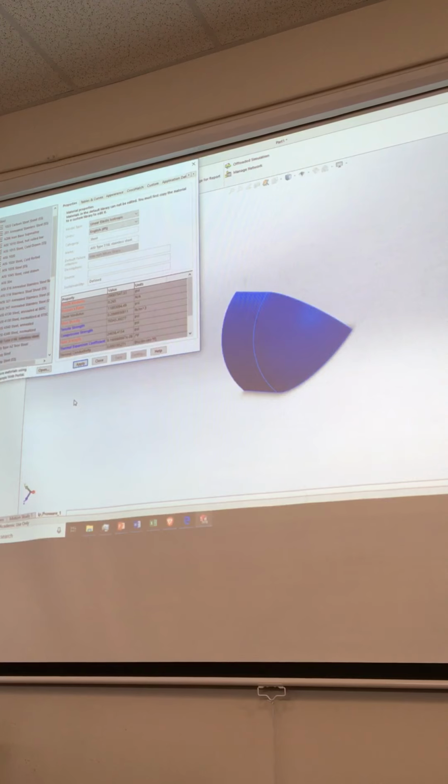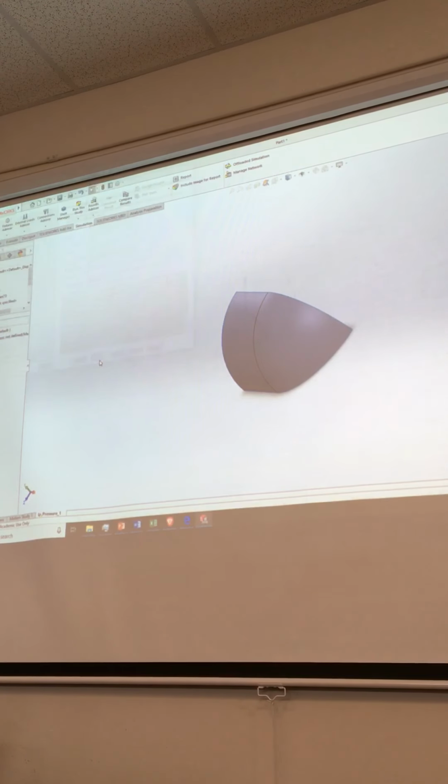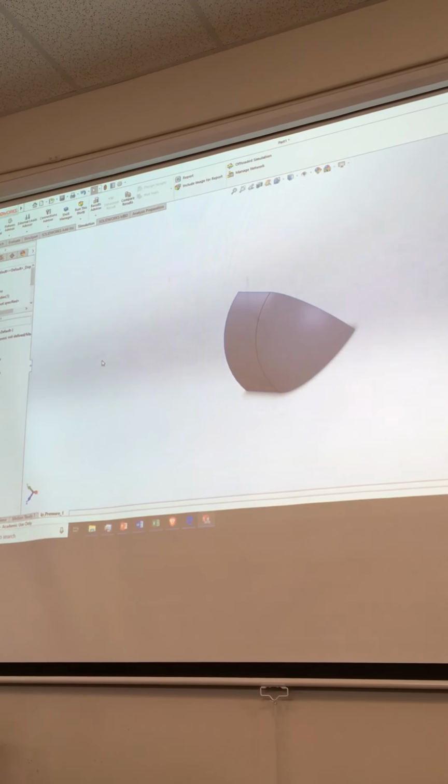It asks for material, right? What are we going to make it out of? Steel? Yeah. Might as well make it out of A36. No reason to make it out of good cold rolled steel, because how is the tank put together? Piece by piece? Yeah, it is put together piece by piece. How do we assemble the pieces? We weld them. So if there's any cold work in it, it's gone.